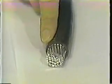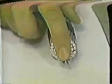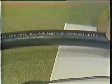Stranded wire is usually used in the larger sizes, but this is primarily to make the wire more flexible and to allow a steel center core like this, which makes a stronger wire for spanning long distances. Exact diameters and amperage capacities for various insulation types are spelled out in the National Electrical Code. Normally, identification is printed on the outside of the insulation, with wire size first, then this is followed by some letters. The letters stand for the type of insulation used on that particular wire.